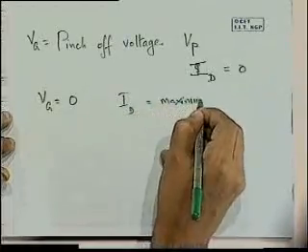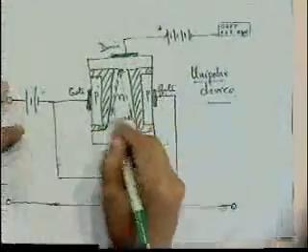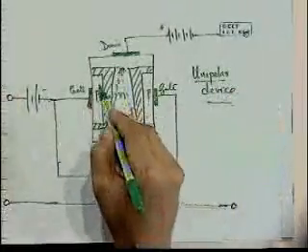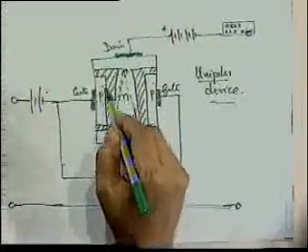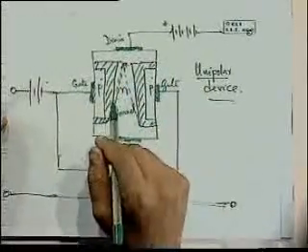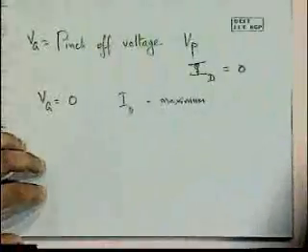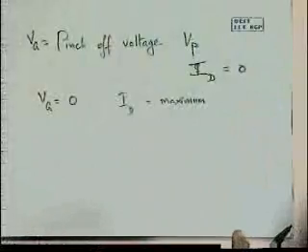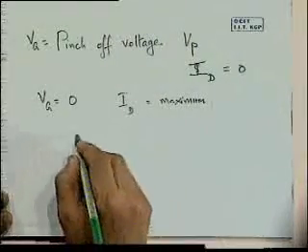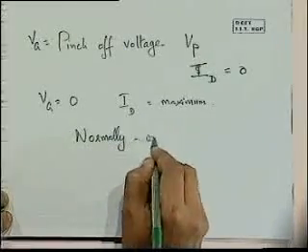through the source to drain, because there is no depletion layer in the channel. If the gate is not biased, there is very small depletion layer, I won't say none, but very small, that is there as our equilibrium built-in value, W naught, and then you get the maximum current. So this is how we regulate it. You apply a different voltage, increase the negative voltage, and you will get a different current. So this is also referred to as a normally on device.